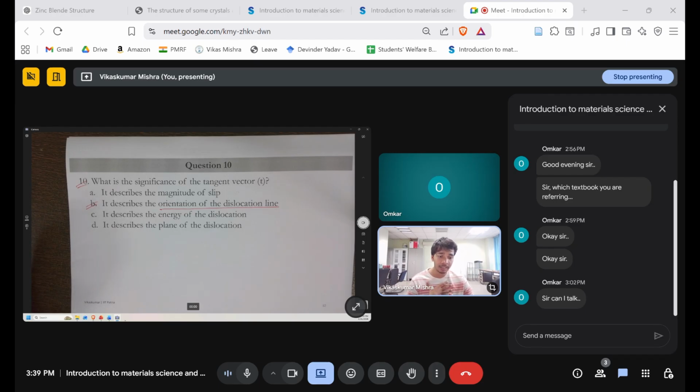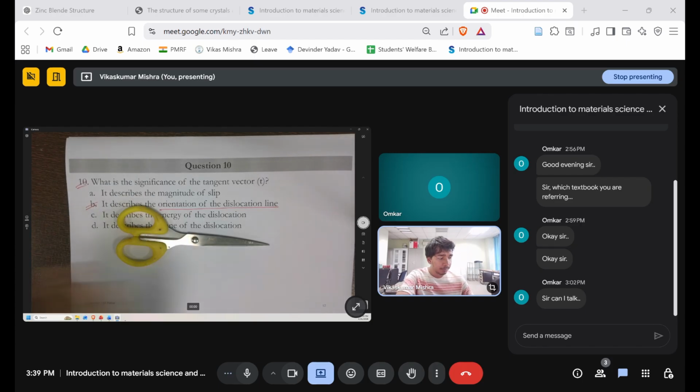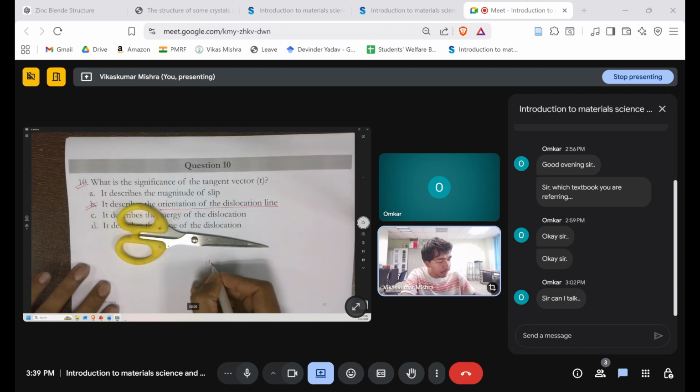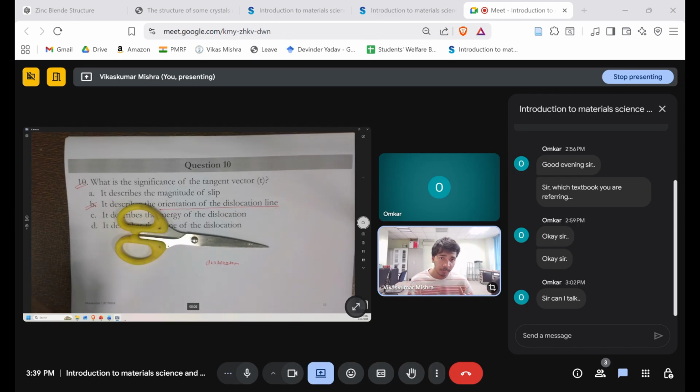It's the external condition. Let's say I take a metal and a hammer and I beat it multiple times. I'm creating hardening, additional stress in this specimen, I'm creating dislocations. So it's the external stimuli doing this. If it is a copper wire, try to bend it. If you try to bend it again, you will require more force.